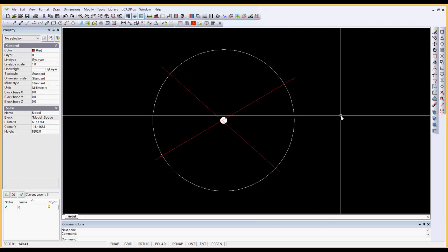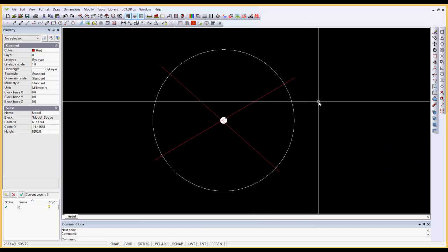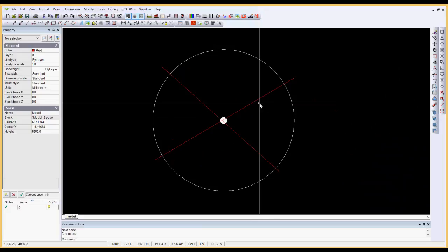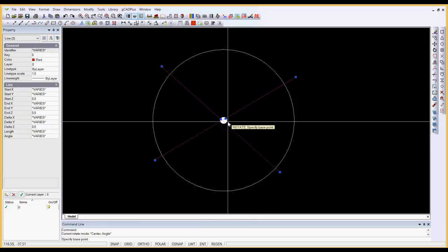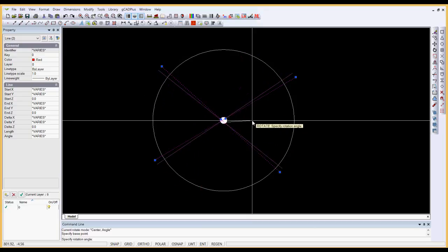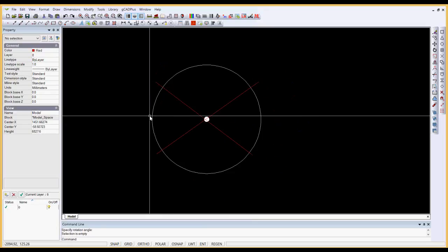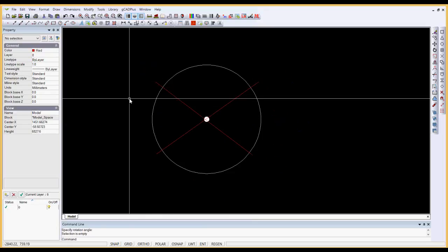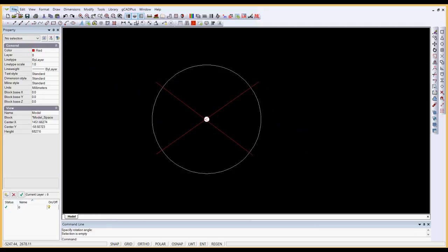So there's a drawing which currently has no name, and we're going to use it as an indicator of an existing tree. You might want to rotate that so that you get the cross symbols looking a little better at a slightly neater looking angle. Now to use that as a block in other drawings, we simply save it as a drawing, and I'll put it in my temp folder.